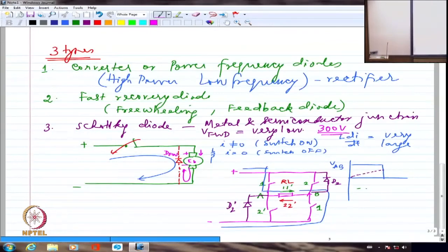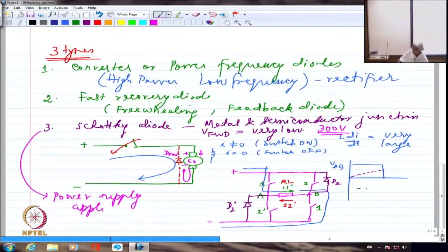These are mainly used in power supply applications. Again, power supply applications, because if you look at many of the regulated power supplies that we have in the lab, which are definitely not SMPS, they are regular linear regulated power supplies. Those will be 15 volts or 5 volts or 3.3 volts and so on. Out of that, instead of dropping 0.5 volts, if you drop only 0.2 or 0.1 volts, it's better. You have a better regulating capability. So you would like to reduce the drop as much as possible in power supply applications. Because of which normally Schottky diodes are used in power supply applications.